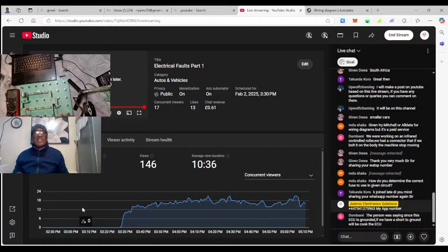But you still get sensors having a short to ground. Very possible, because once a power wire touches the body or the chassis, and maybe it's been rubbing and then it loses insulation and then it touches the body and the chassis, that's it, short to ground straight away. Yes, ECUs can be protected, but do not bank on that, because I've seen youngsters fry ECUs.